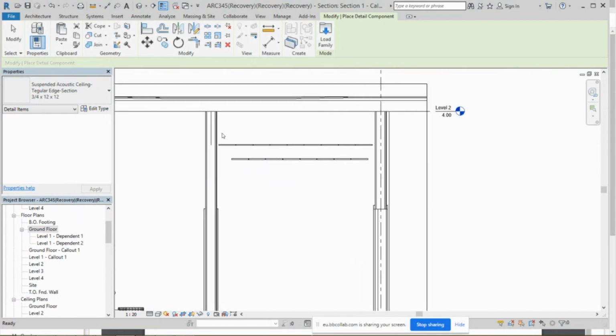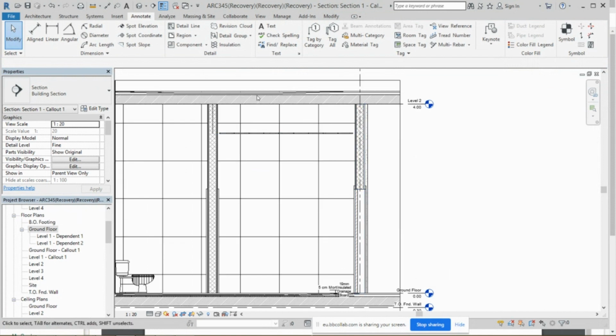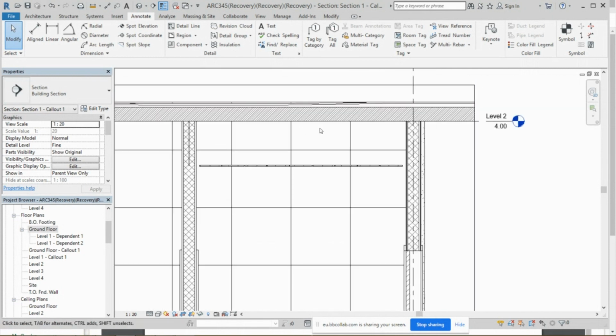Also, one of the things that we can do is that if we decide to make a suspension ceiling like this, we don't want to make the ceramic going up to the ceiling here. We think about it this way: we're not making a drawing for architectural presentation, we're making a drawing for actual construction. So here it's expensive for me to just make the ceramic continuous, given that I'm hiding a portion of it. So what's the point of making this ceramic?